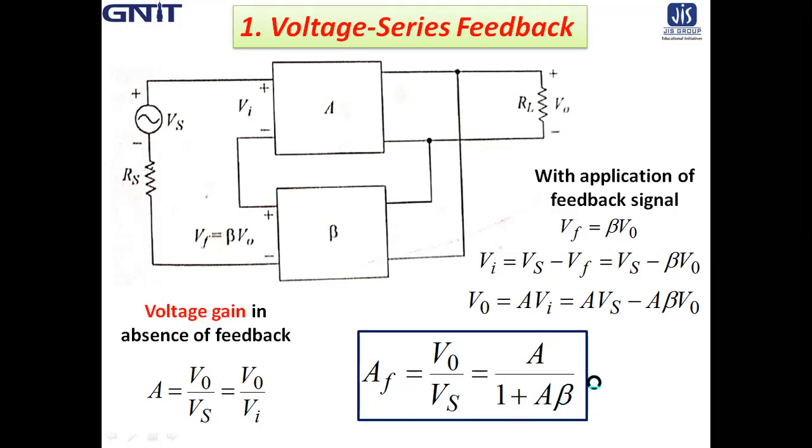Next, we have to calculate input impedance. For all these four topologies, first you have to determine the closed loop voltage gain, then the input impedance and then the output impedance. So this is the closed loop gain for the voltage series feedback topology. Now, what would be the input impedance?